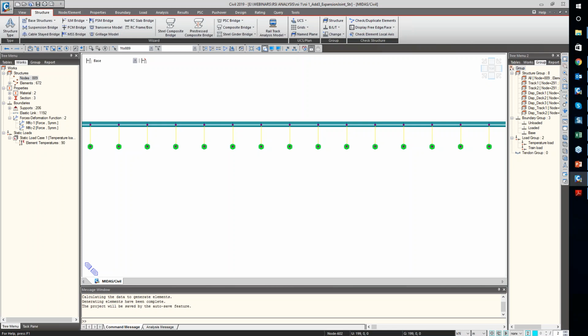Should the string be modeled with the same pre-stiffness at each end? In that case, I'm not sure what you mean by string. Can you elaborate on that rail string? Basically, what you are saying is true. The larger the span, the more stresses we will get in our rail, because bending will be more and the structure will become more flexible. But I don't think we need to model it with pre-stiffness at each end. First we will take it as a rest condition, and whatever stresses are coming because of the loads, we need to consider that.